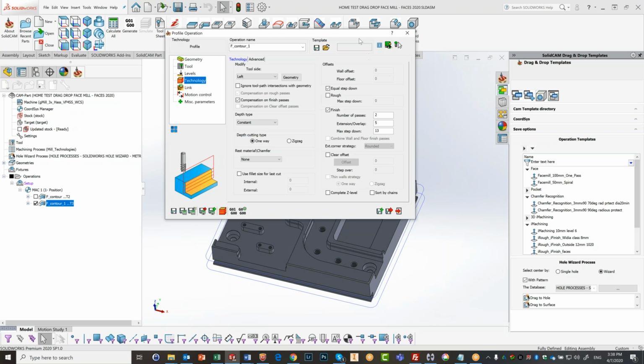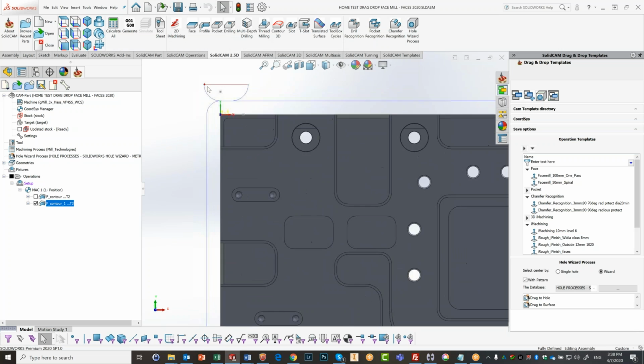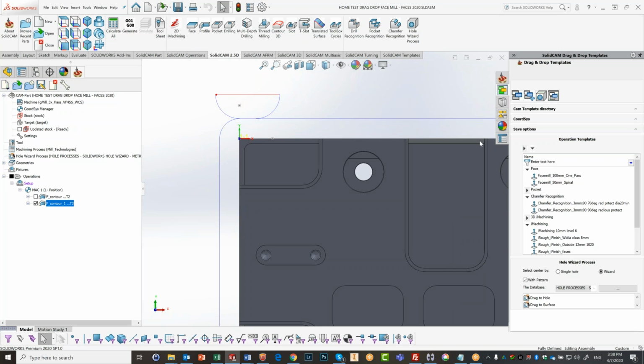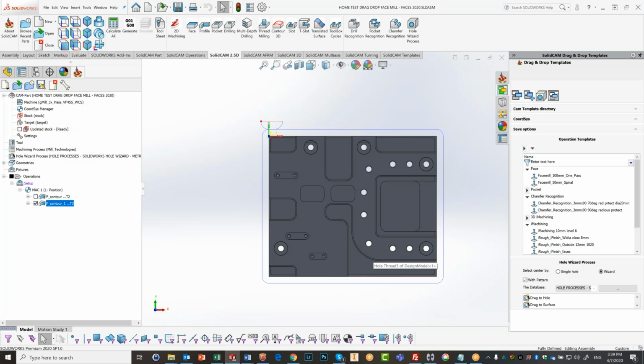Let's take a look just at my tool path, from the top view. You'll see, here's my lead in. It's going around the part. Now, when it got back to this spot, it went another 5 millimeters along the geometry and then went out. So it extended the geometry to make sure it's covering that area. Now, this is a particular edge, but let's say this was a round part. There is no edge over here, so it normally would leave a mark if I would go exactly to this point. This allows you to extend that area over there. Any questions at this point?